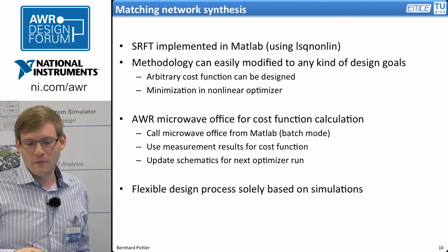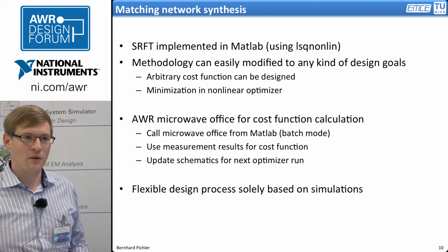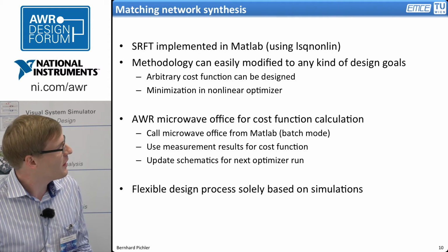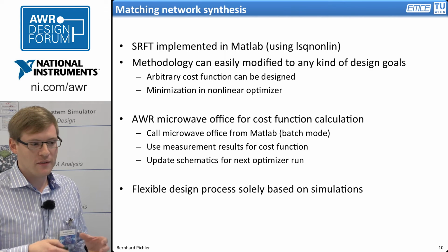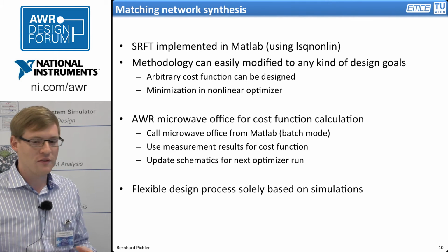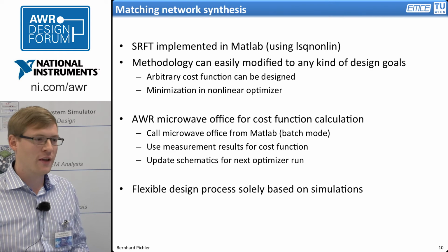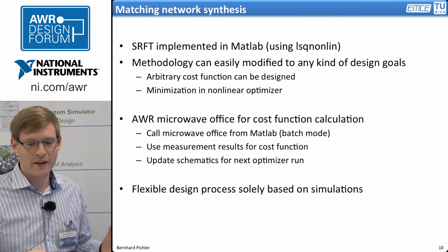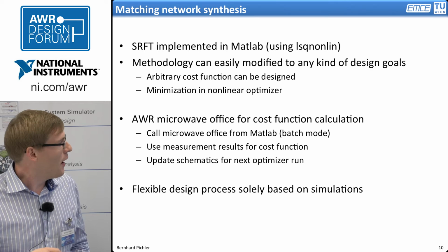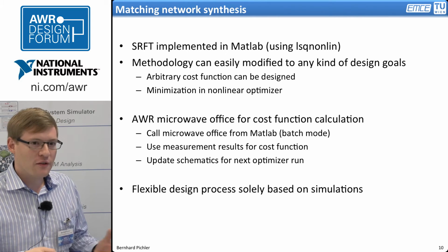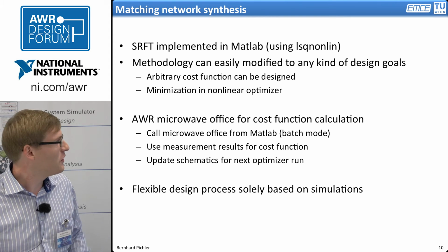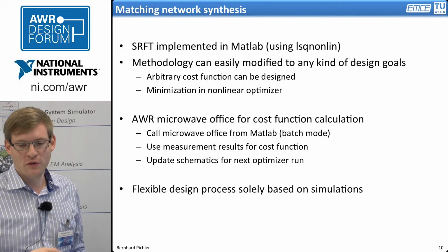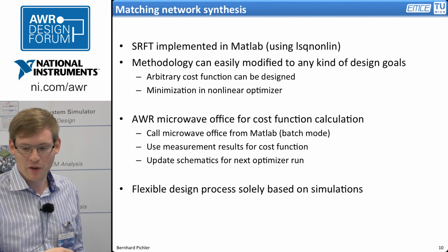The good thing about this methodology is that it's very flexible. I implemented this whole optimization process in MATLAB, using a least-squares nonlinear optimizer. You can design your cost function in any arbitrary manner, so it's very flexible. You can use several different power amplifier topologies and define it as you like, depending on your design problem. You end up with a very flexible solution to solve such double matching problems.